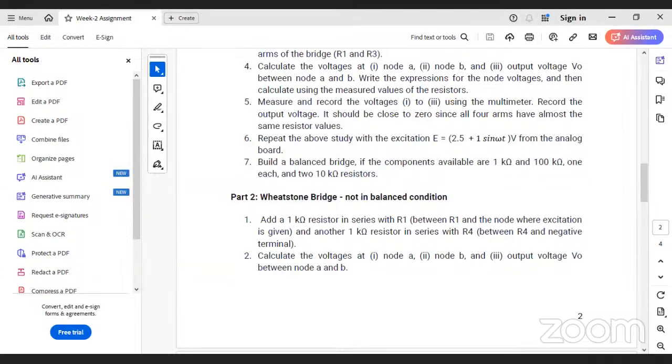It will show, but in reality, when you connect to an oscilloscope, the actual output from your ADALM kit will not be the correct one. There will be some discontinuous part. So please disable that repeated sweep if it is there when you open that Pixel Pulse app.